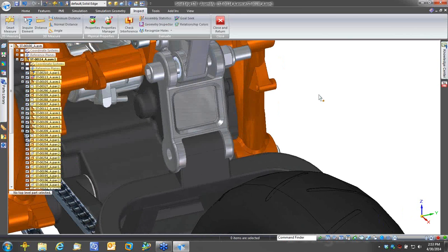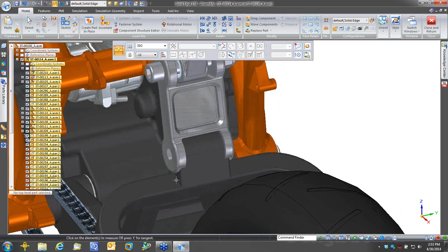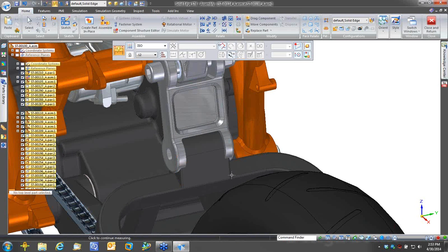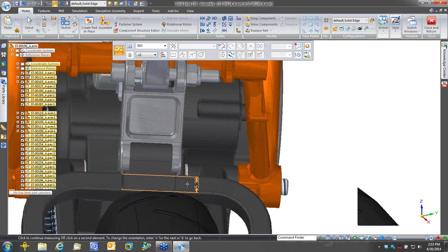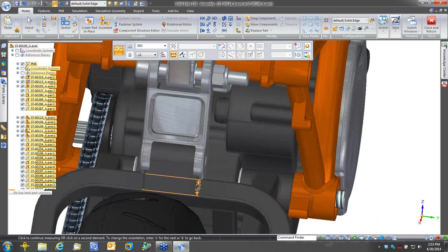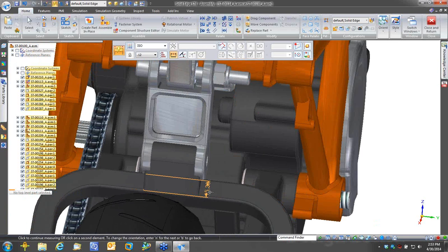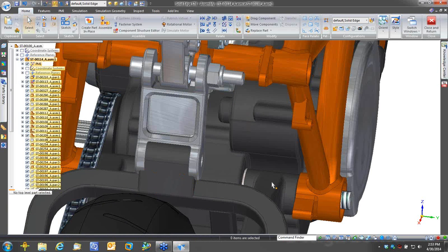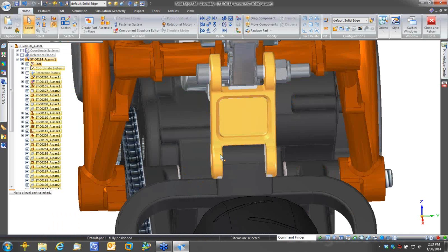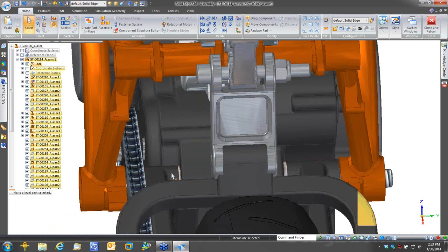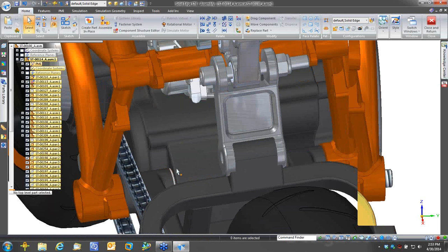So one of the things I may want to do is I need to see what is the actual width of our connecting feature here. So as I rotate around and I find the edge, what is the width? And it looks like it's 50 millimeters. And so I need the spread distance in my mounting arm on the internal to be at least that value, probably a little bit more for clearance purposes.